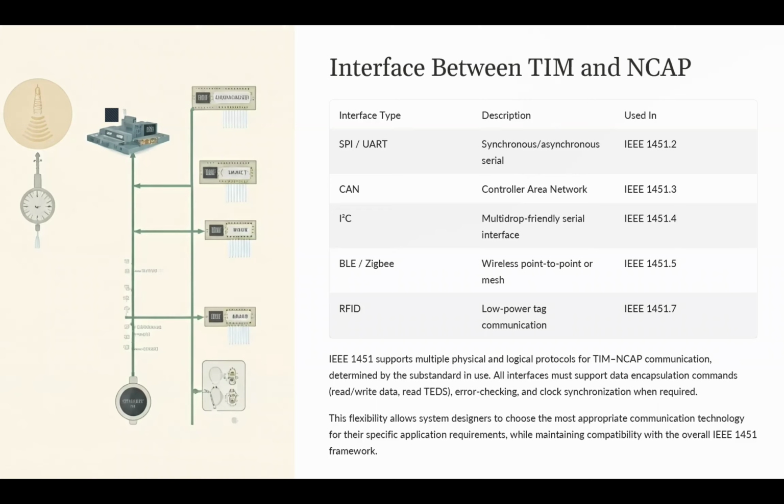We have another type of interface, which is I2C, a multi-drop friendly serial interface. Part 4 of IEEE 1451 covers that type of connection. I2C is a simple, cost-effective bus for mixed-signal applications, supporting analog signal transmission and a digital TEDS overlay.